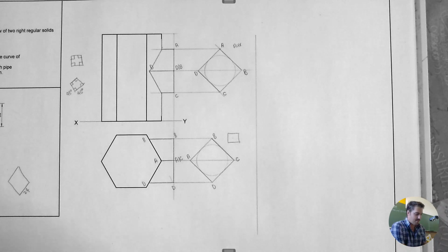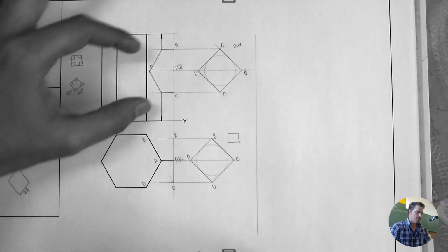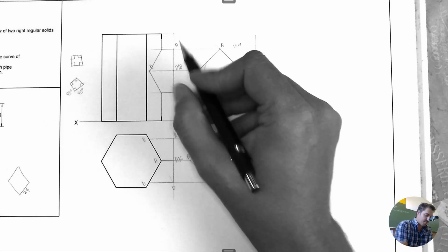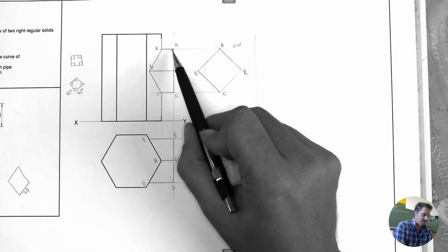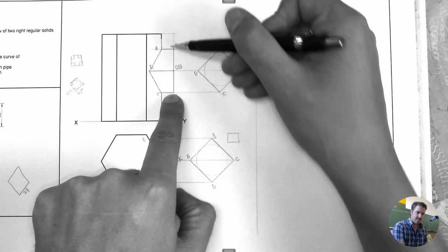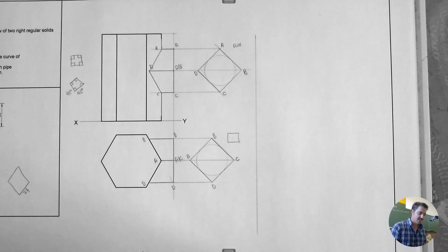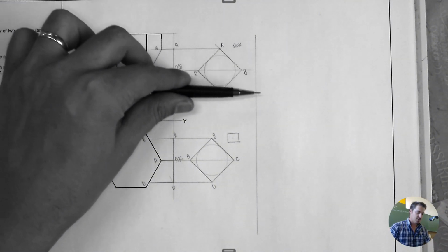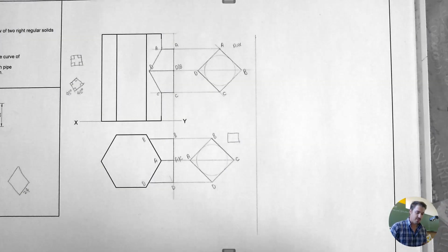So essentially what's happening is I'm using this branch pipe and removing it from this front view, and then I'm cutting it open on the seam. They told me AA is supposed to be the seam of my drawing. So if I cut it open here and turn it around, so the flat side, this base, is in line with this line, and I put point A here, then you would see it rolling up in segments, A to B to C to D back to A. That's how it's supposed to unfold.